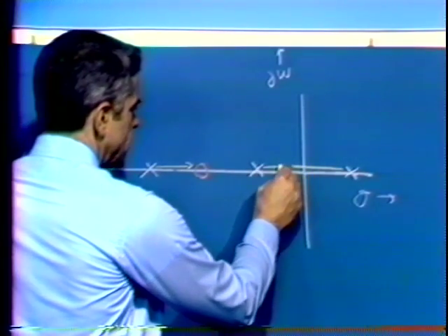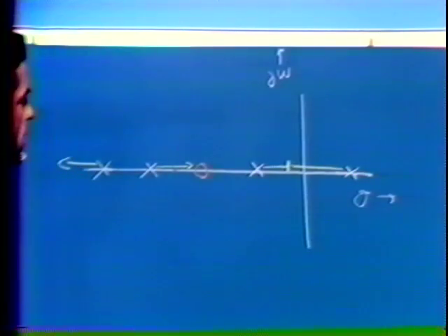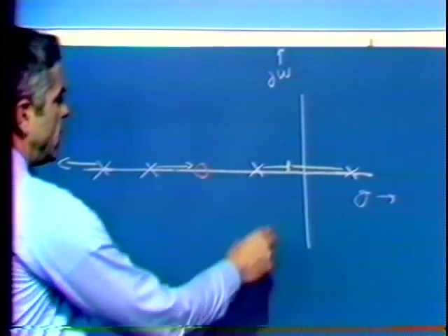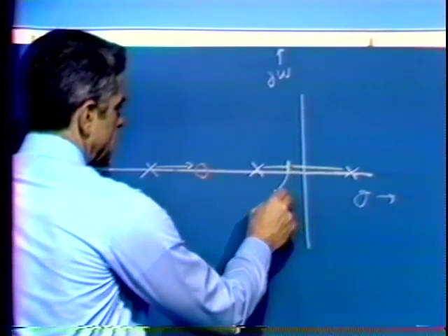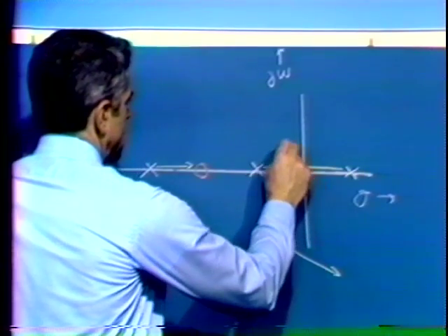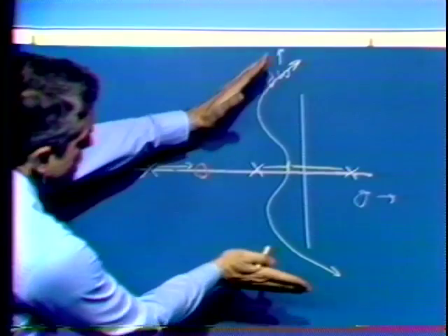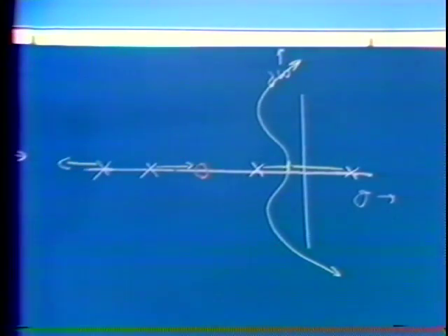So these 2 branches meet at a point somewhere in the left half plane. And again, depending on the exact spacing involved, we might end up with a diagram possibly that did something like so. Eventually the branches go off, making angles of plus and minus 60 degrees. The third branch, of course, goes off at minus 180 degrees.